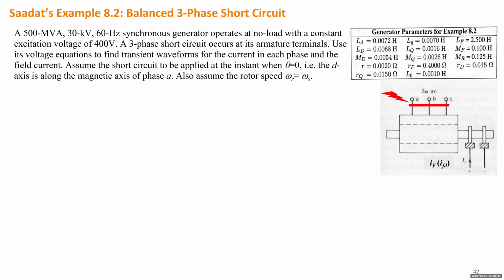So that is our good model. We can utilize that model to do some simulation. For instance, we can add a three-phase fault to a generator. So let's assume the generator has a short circuit connecting all three phases of the terminal, and assume we have all the parameters, and they are all constant. This is a good model. We definitely can do such a calculation.